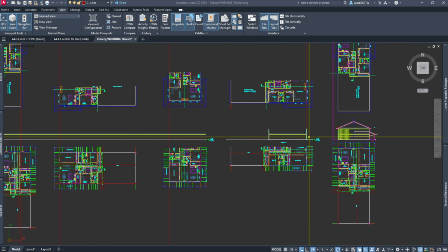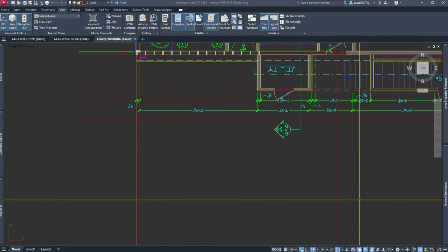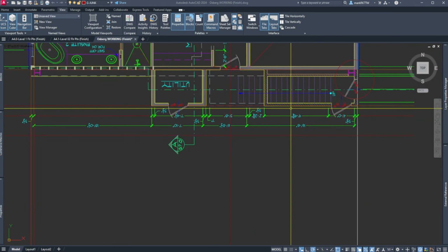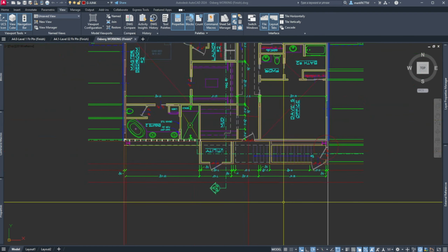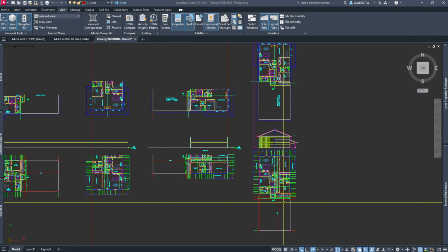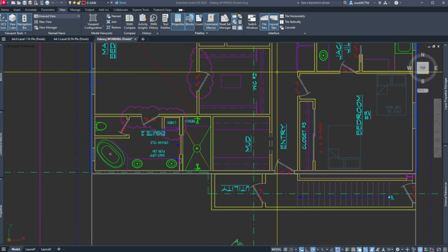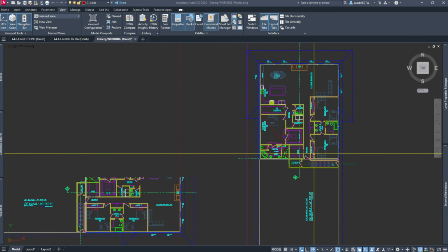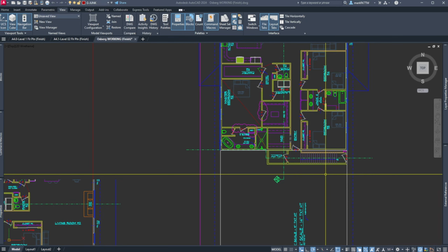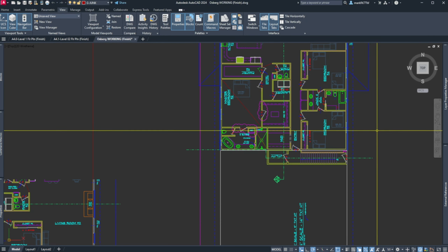And being that a lot of their components are pretty standard, I think I'm pretty safe there. So here is my actual stairs. And I do like to verify that I've got my alignment working correctly. So I'm in my junk layer. So I'll do XL vertical. And I'm not in the drawing. XL vertical. And then I'm just going to drop it on that first tread.